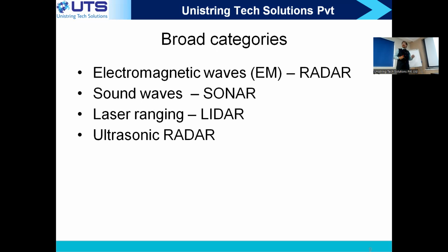This is very interesting. You get a lot of kits on electronic sites and all. You can buy an ultrasonic sensor which has a simple ADC and do all radar processing, and that's really fantastic. If somebody wants to master radar, you don't need to have a crore worth of radar, whatever we build. Just have an ultrasonic transmitter and an ultrasonic receiver. The ultrasonic transmitter should be driven by a DAC from your microcontroller or microprocessor. The ultrasonic receiver streams samples with an ADC into your microcontroller. All the things of radar you can learn this way, whatever we are studying today.